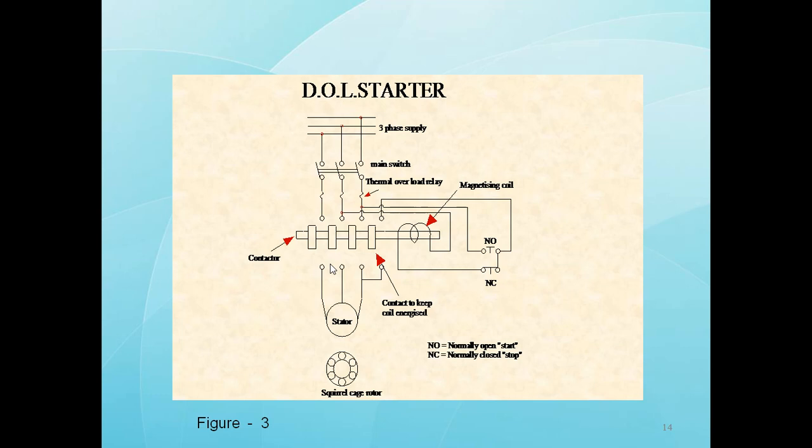So what is the meaning of this? The motor continues to get supply even when the on switch is open. Why? Because the contactor coil will get supply through the contact terminals, and this is called the hold on coil. That is, you press and release, then it is all magnetized, and it pulls in this contactor, and all these open contacts are closed.